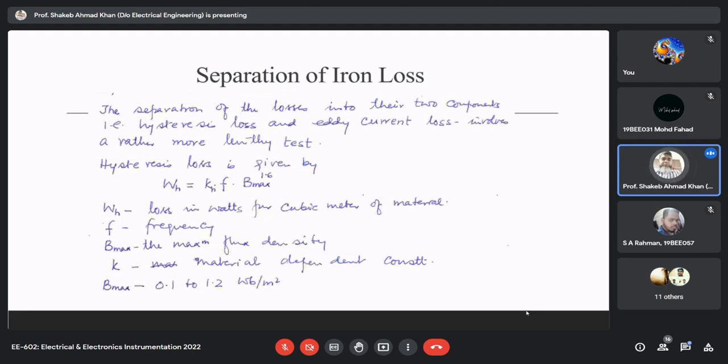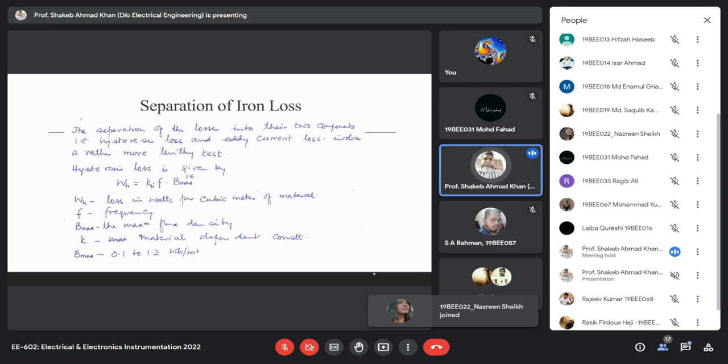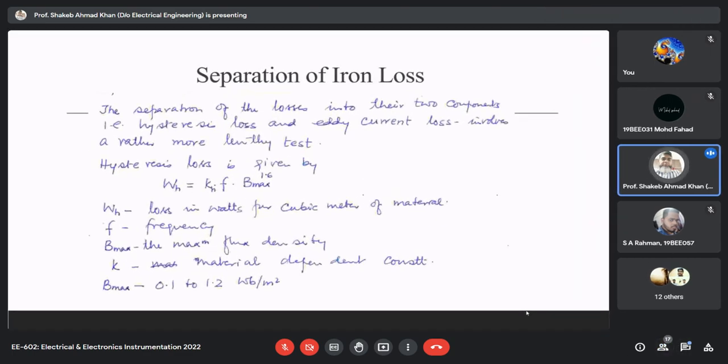There is a straight line that represents the losses, and over there you are required to divide the core loss into two parts, eddy current and hysteresis loss. But at that time it is assumed that it is half and half. Till now you didn't study how we can separate them quantitatively, accurately. So here there is a technique through which we can separate